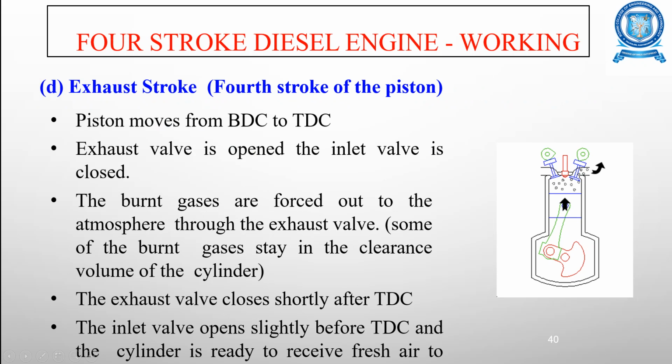The exhaust valve closes shortly after the top dead center position, and the inlet valve opens slightly before the top dead center, and the cylinder is ready to receive the fresh air into the combustion chamber.